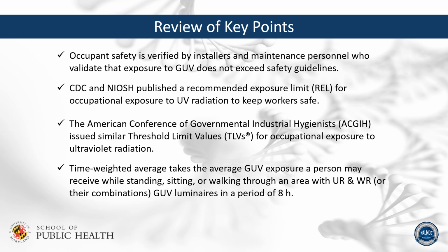The American Conference of Governmental Industrial Hygienists issued similar threshold limit values for occupational exposure to ultraviolet radiation. Time-weighted average takes the average GUV exposure a person may receive while standing, sitting, or walking through an area with upper room and/or whole room GUV luminaires in a period of 8 hours.